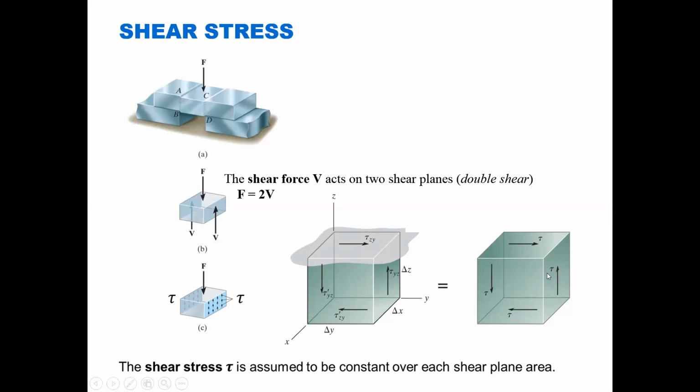Okay, so this shear stress acts on an area, and that area is delta x times delta z. If we take the increment of shear force that's acting on that area, and we sum up all of those incremental shear forces and all of these little areas across here, we will end up with just the total shear force, V, divided by the cross-sectional area.